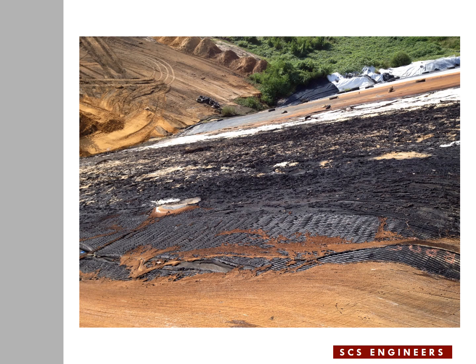Here is the damaged area after removing the tires and plastic sheeting. You see this is the geosynthetics, which were 4 layers, and as I explained earlier, completely burned out, and the subbase is exposed as you see in this slide. In the foreground you see the lower layer of the geogrid exposed and visible, and I'm going to take you one step at a time through the repair process.